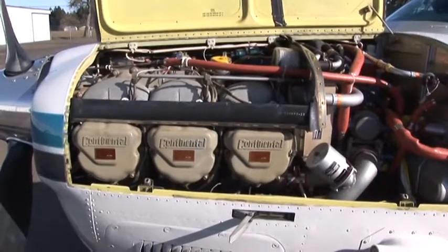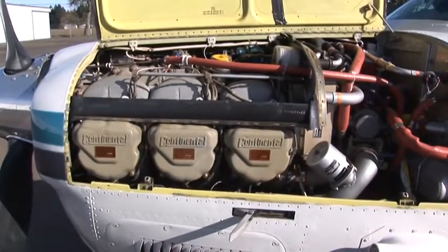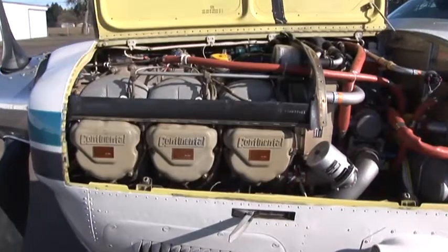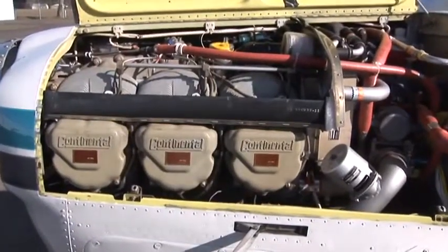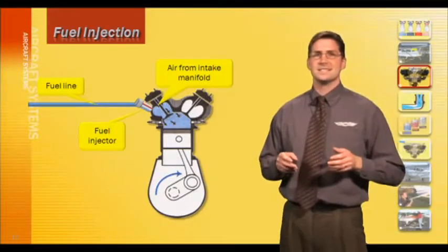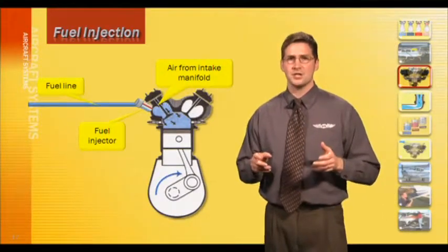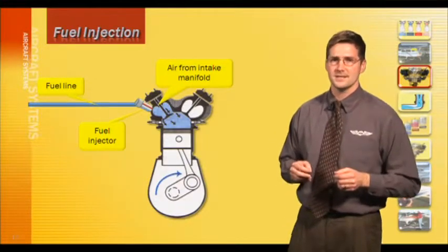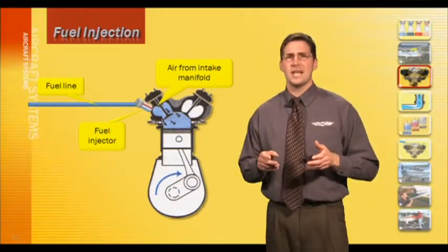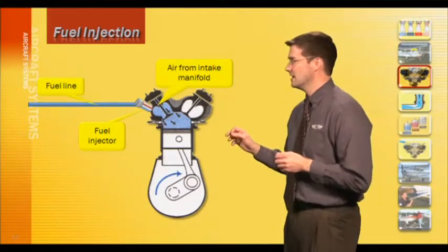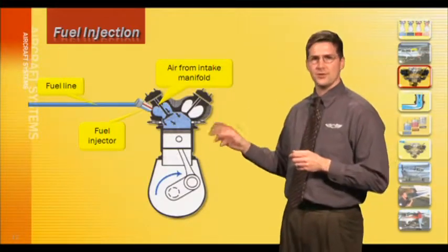If your aircraft has fuel injection, there will be no carburetor in the engine, and the fuel will be directly injected into each engine cylinder. On fuel-injected engines, fuel is injected directly into the cylinders rather than being vaporized in a carburetor. Since the cylinder is hot, there is not much danger of icing when the fuel combines with intake air and vaporizes. Both fuel injection and carburetor systems have their own considerations for icing conditions. Let's cover the carbureted engine first.